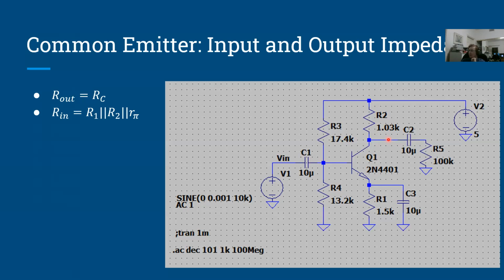There's also the nonlinearity of the transistor. And there's the Miller effect, which basically sticks a large capacitance between the collector and the base, and that reduces your gain as you go higher and higher in frequency. We can take a look at that later.